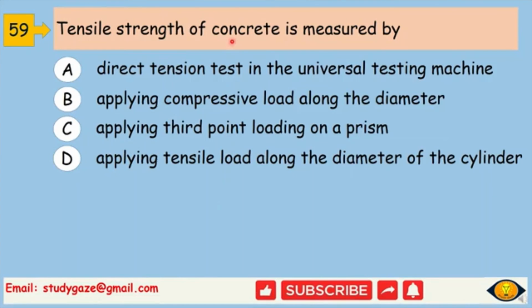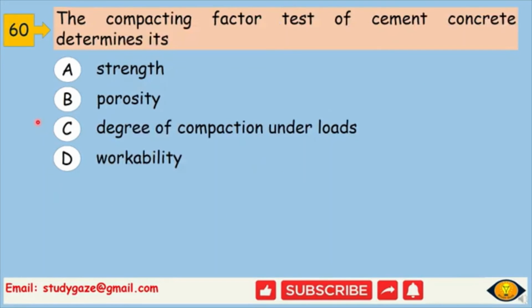59. Tensile strength of concrete is measured by direct tension test in the universal testing machine, applying compressive load along the diameter, applying third point loading on a prism, applying tensile load along the diameter of the cylinder. Answer will be C. Applying third point loading on a prism. 60. The compacting factor test of cement concrete determines its strength, porosity, degree of compaction under loads, workability. Answer will be D. Workability.